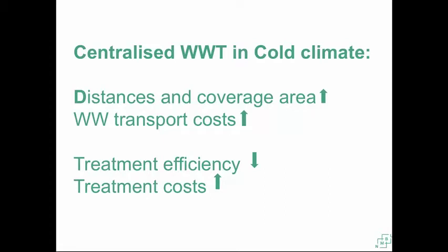So at the end of this lecture, what I want you to remember is that in colder climates, especially in the northern cities, the distances are quite big, and the coverage area per municipality is also increasing, which also means that the wastewater transport costs are increasing. And the treatment efficiency is going down because of the colder temperatures, which means that to match the treatment efficiencies, the treatment costs are going up. So I'm going to show you some slides,